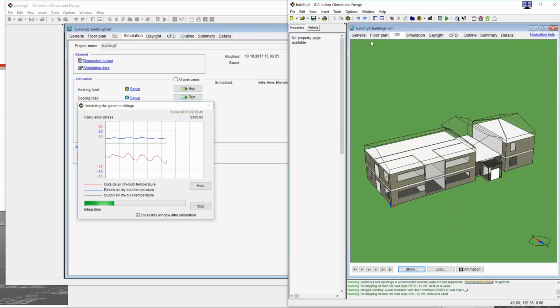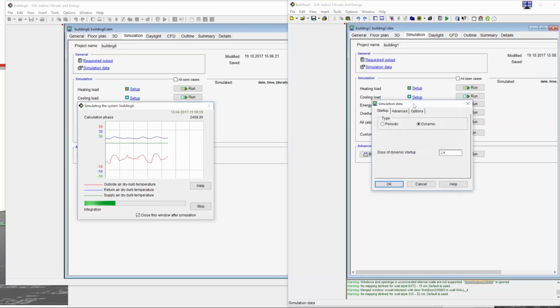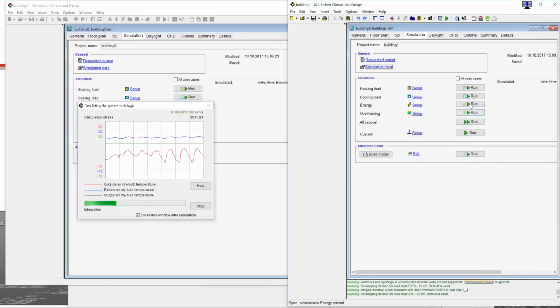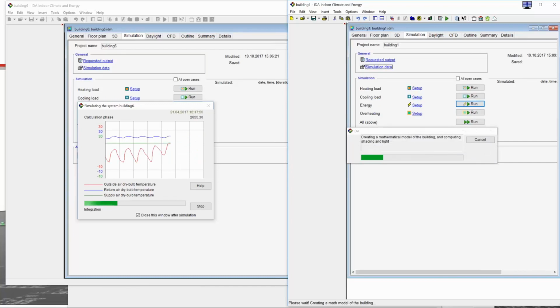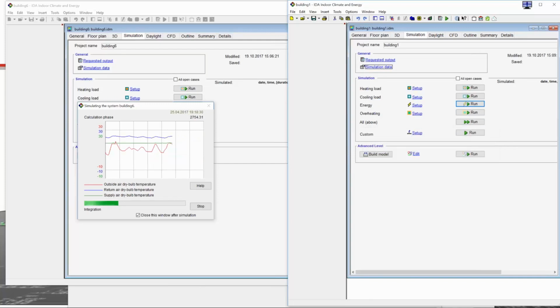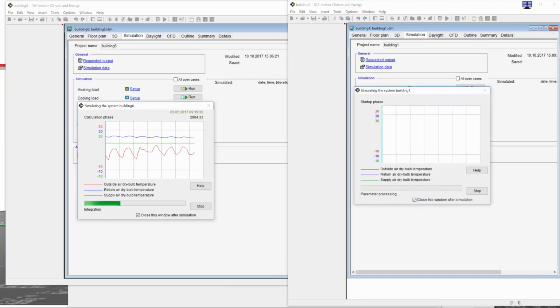Another thing to speed up is the time split parallelization. If you go to simulation data, at advanced, you will see here use time split parallelization. When now running this model, first you will observe that it takes a little longer until the simulation starts, because now the model is split into some parallel models that will be run in parallel. It will be the simulation period that is split. But soon the simulation will start.